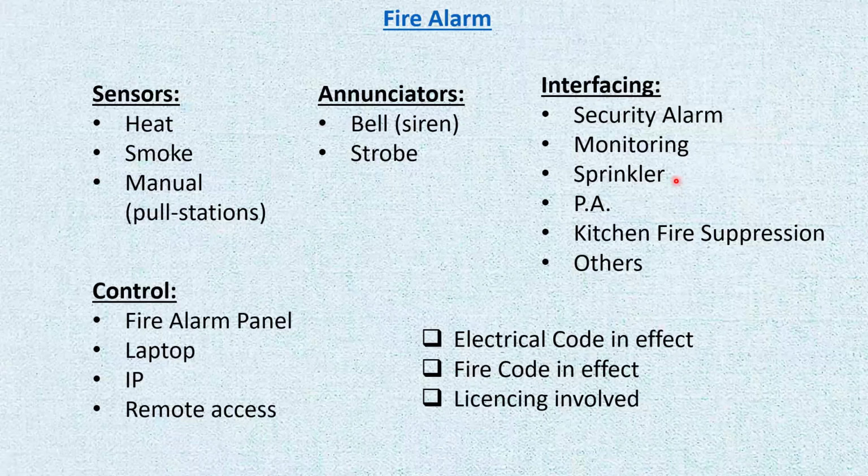Okay, what if you want to install a sprinkler system in a parking garage that is outside? What's going to happen in the winter? The water is going to freeze in those pipes and it's going to burst those pipes. So these are dry systems. In those pipes, there is no water present at all times. It's just air under pressure. When something happens, things trigger and the water starts flowing through the pipes. So there will be dry systems.